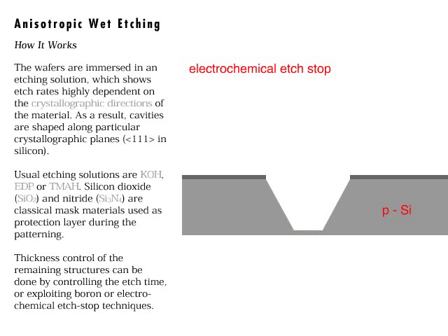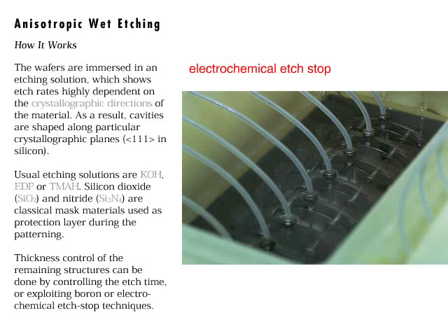Electrochemical etch stop can be effectively performed on a normally n-doped silicon layer in which resistors can be integrated. Usually, an epitaxial n-doped layer of silicon is grown on a p-type substrate to form a p-n junction. The etching will stop at the junction if a reverse voltage is applied. Electrochemical etch stop is a precise, reproducible, and reliable technique, but requires complex apparatus to electrically contact the wafers in the etching solution.